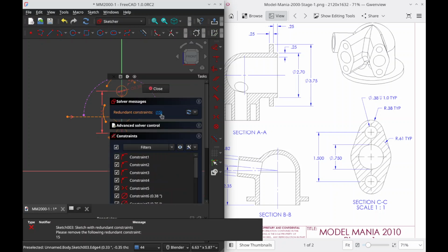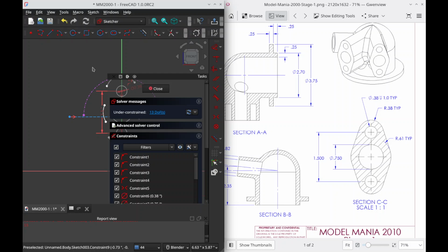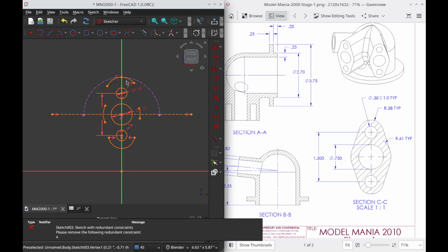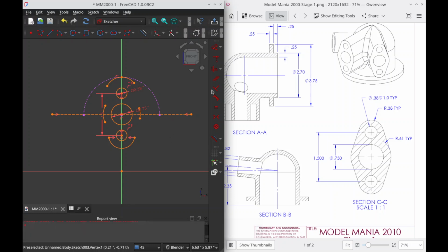Where's my thing here? Remove any redundant constraint. And we can't move it side to side. It's construction geometry, it's not exactly a center line, so I just stress about how it goes. It doesn't go on forever. Anyway, this we want coincident on there. This point is now fixed. Oops, we have redundant constraints.